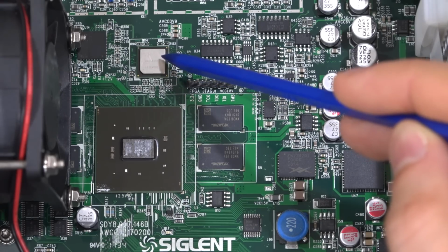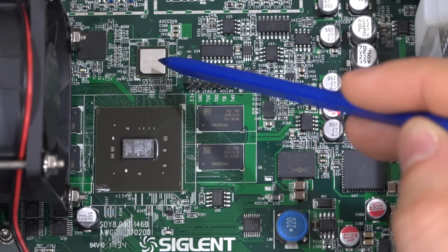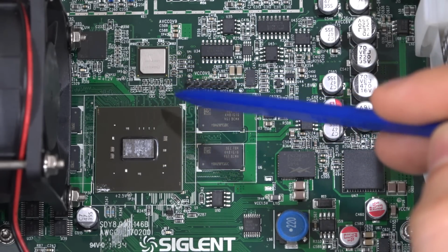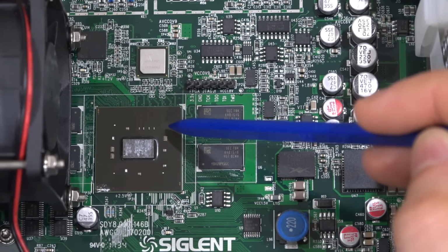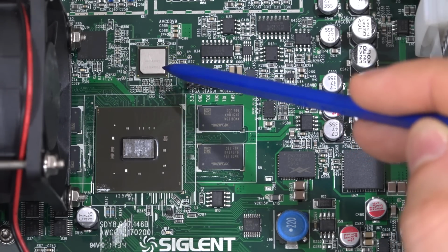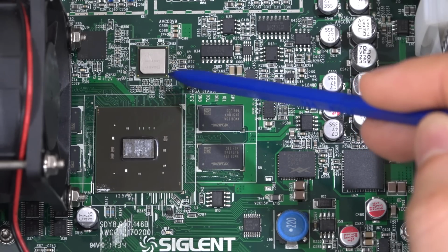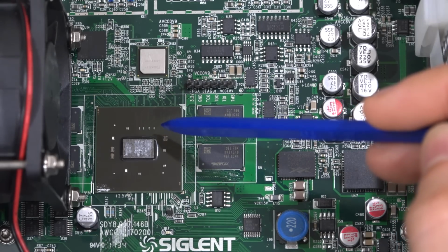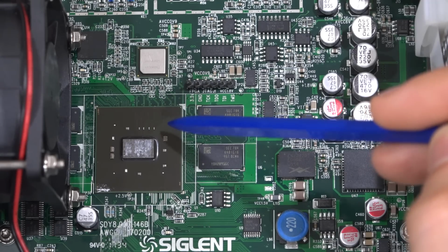Now this DAC itself has 500 megahertz of analog bandwidth per channel. So if you had a sufficiently fast interface, you could potentially create an arbitrary waveform that occupies the entire bandwidth. Now the FPGA on this board cannot do that. Therefore you're limited to a much lower bandwidth than the maximum bandwidth of the DAC itself. But the DAC has some built-in functionality such as interpolation and internal signal generation for up conversion. So you can use those abilities combined with the limited interface of the FPGA to create modulation at any frequency you want up to 500 megahertz. And that's exactly what they have done.